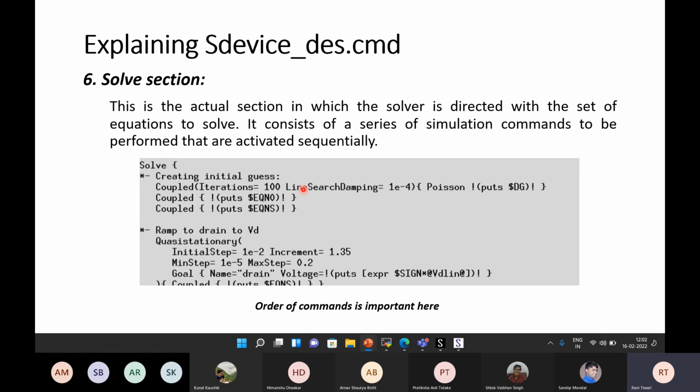So you should have at least 20 or 30 points, at least 10 points, so that the simulator can solve the potential from the source to the potential at the drain, because those potentials are different and things are going to be different in terms of band, in terms of energies. So the simulator needs to have some points where it can actually get a converging solution for all those quantities. So it always depends upon what you're simulating, what your dimension is, and whether you can get a good solution out of it. That's how you need to define your mesh.